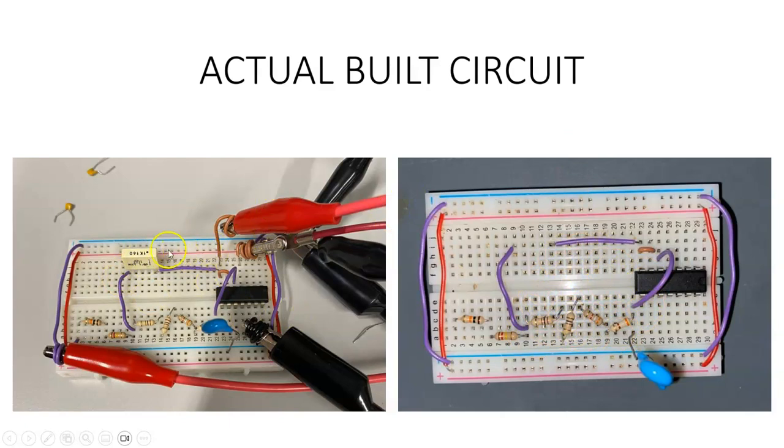So in the picture on the left here, we have the probes inserted into the breadboard. Right here on row 26, we can see that's where we power our op amp. So this probe here is connected to direct voltage, DC voltage, 15 volts here and here. So on this whole line 26, we have the VCC plus, which is on this side here, and VCC minus, which is represented with the black here.